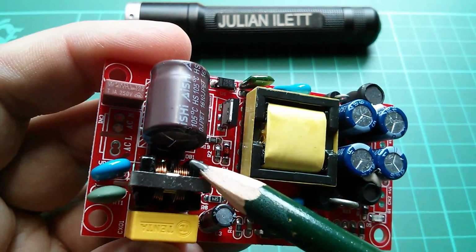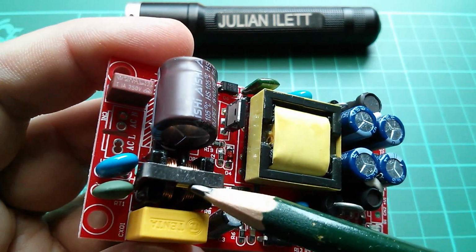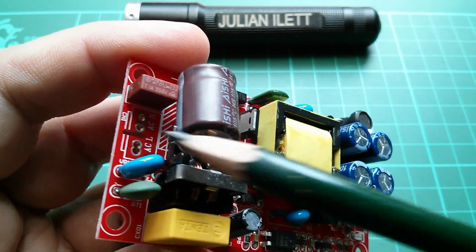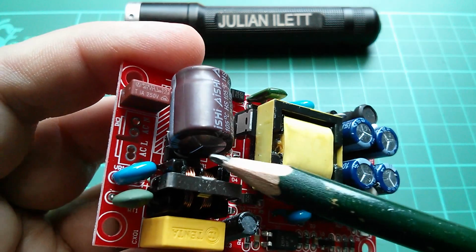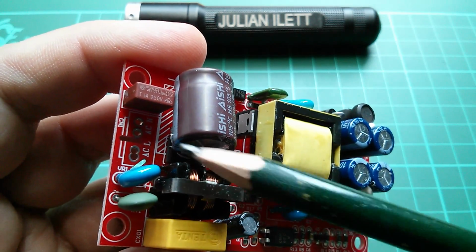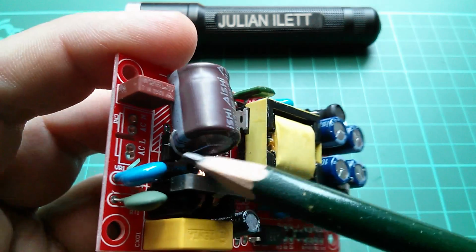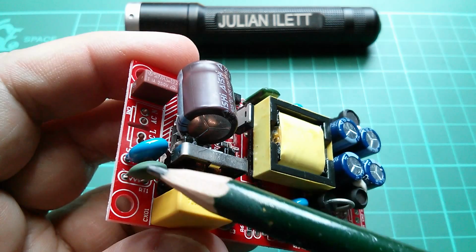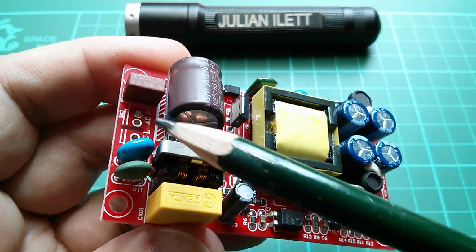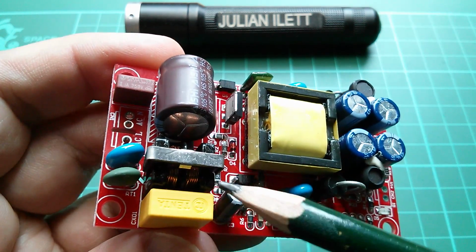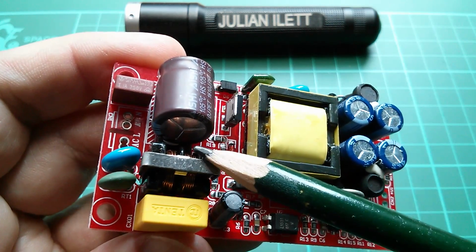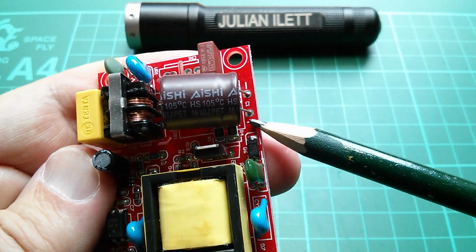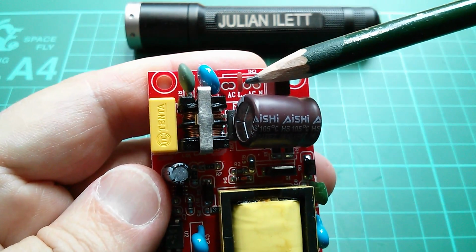Now, because there's a bridge rectifier down in there after the choke, I don't suppose it matters which way round I put my DC, because it's going to get rectified by two of the bridge rectifier's diodes. So it's, well, steered more, not so much rectified, but steered into the correct polarity on the capacitor. So I can put my DC either way around there. None of these other components are going to make any difference. The capacitors won't affect DC. The DC will flow through the two choke coils, and we'll end up with the same thing on here, a DC high voltage, exactly the same as what would happen if you put AC into here.